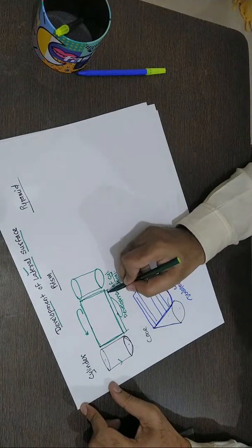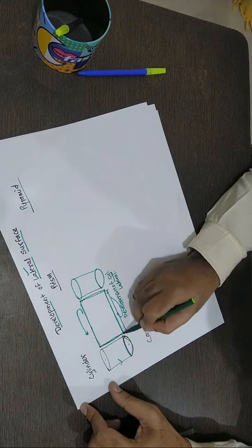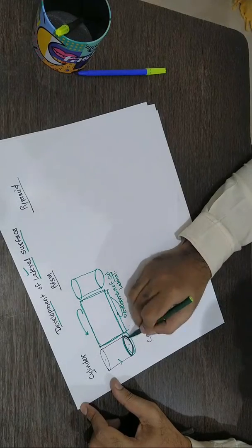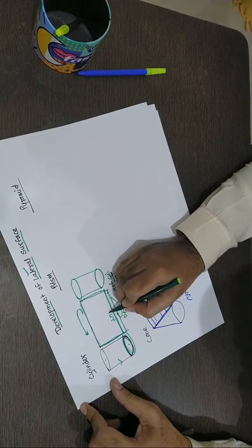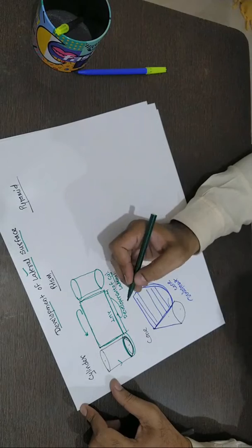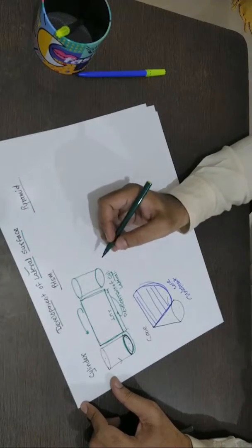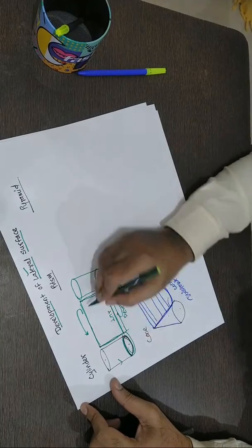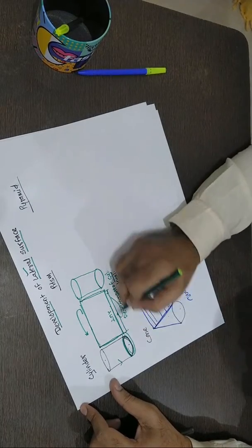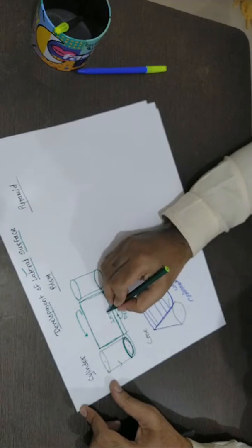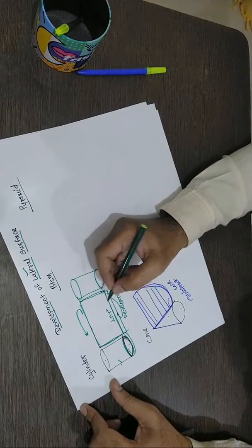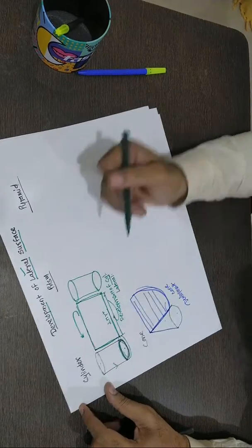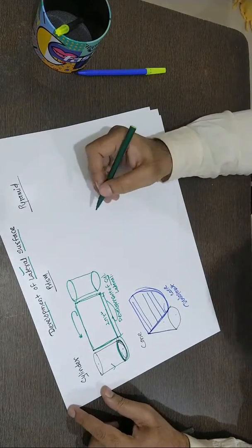This length is exactly equal to the length of the surface, which we know is 2 pi r, or pi d, the circumference of the circular base of the cylinder. So for this development, as a rectangle, the length is 2 pi r or pi d, and the height of the development is equal to the height of the cylinder, which is given in the numerical most of the time.